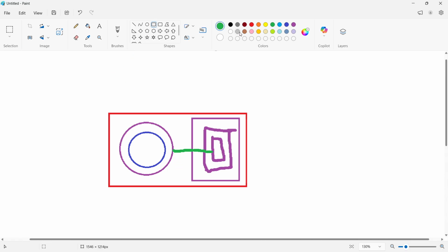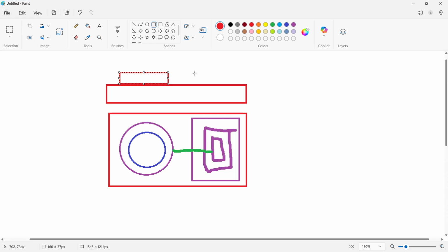If you look at the front view, I have one toolpath here, another toolpath here. When the software connects between the groups like this, it depends on the settings, whether it could be direct, it could be blend spline, it could be retract to feed distance, retract to rapid distance, or retract to clearance area.